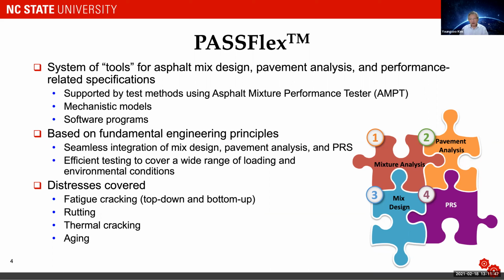In order to do the pavement simulation, you do need to cover a wide range of loading and environmental conditions, and mechanics allow you to do that. Distress is covered for cracking, both top down and bottom up, and rutting and thermal cracking and aging.